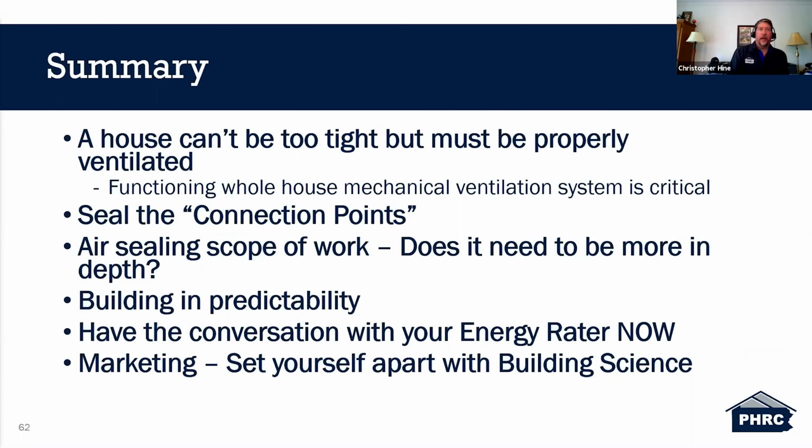Working through this summary, a house can't be too tight, right? You just have to make those additional measures to achieve that whole house mechanical ventilation. And again, that's out of the scope of this webinar, really diving into that whole house mechanical ventilation. But there are three choices: exhaust only, supply only, and a balanced ventilation system, right? And if that exhaust only option is working for you at 5 air changes per hour, you really need to take a look at that when we move to 3. It's always good to be looking at that as a good, better, best approach.